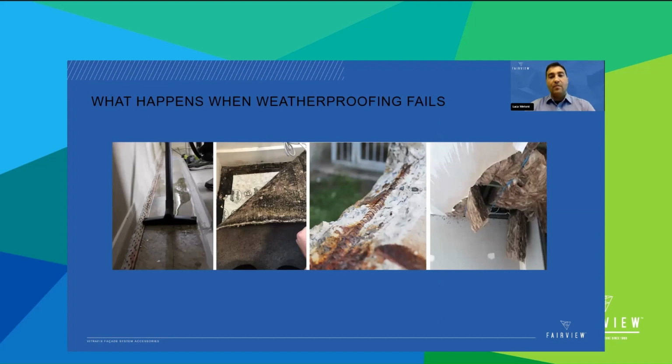In every climate, moisture is a persistent challenge for buildings. Whether it comes from rain, snow, or humidity, moisture can penetrate cladding and damage the underlying structure. Without effective moisture management, buildings risk mold growth and material deterioration, which lead to increased maintenance costs and can even impact occupants' health. To address this, the building codes have evolved to require or encourage moisture control measures that extend behind traditional water-resistant barriers, previously known as WRBs.